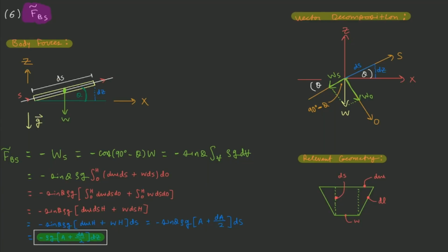If we draw our O-axis and our S-axis, you can see there's a component of W along negative S and along O. We don't care about the O component, right? We only care about the S component, and it's negative, according to our depiction in the free body diagram. So FBS is just equal to negative WS, or negative the S component of the weight.